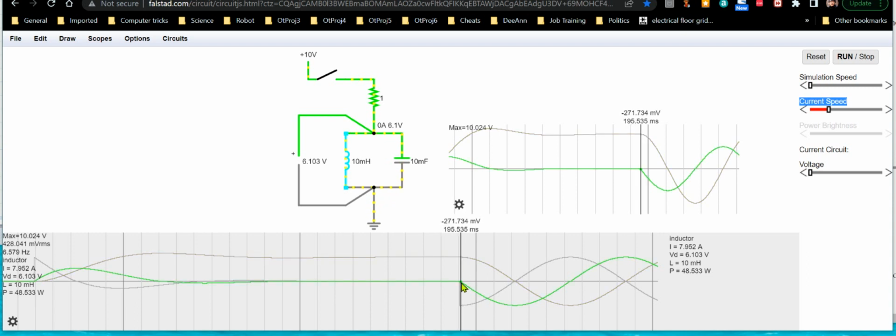The inductor has 0 volts across it, right? Because it's sitting there happy. But once we've taken it off the charging circuit, that inductor starts discharging into the capacitor. The inductor is sitting there at 10 amps. It'll do whatever it takes to maintain this 10 amp current. It has a limited amount of energy, but it does its best to maintain that 10 amp current.